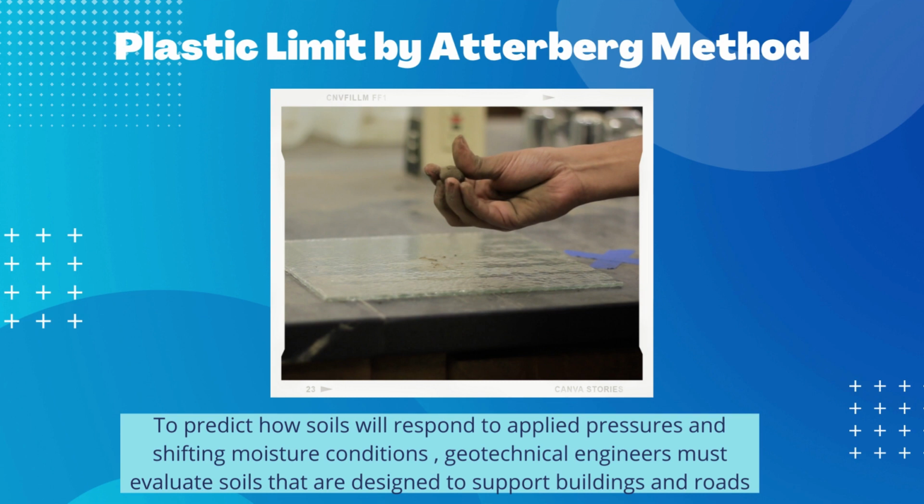In order to clearly characterize the boundaries between these states, solid, semi-solid, plastic, and liquid, of clay and silt, Atterberg limit tests are important for identifying the moisture level at the sites where the physical changes occur. The behavior, reliability, and strength vary noticeably at each level.